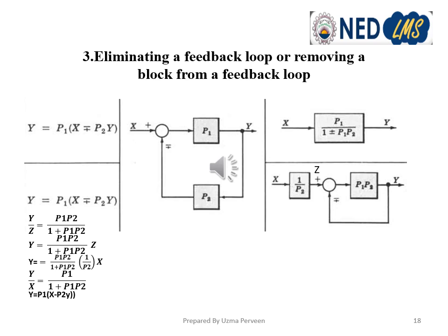Here in the B part, we can see that we have simply replaced the feedback path with a unity feedback path, in which we have removed the feedback block and inserted a block 1 upon P2, which is the reciprocal of the feedback transfer function, with the input x. We can prove it simply. The rule is again that we should get y equals to P1 into x minus plus P2y after the transformation.